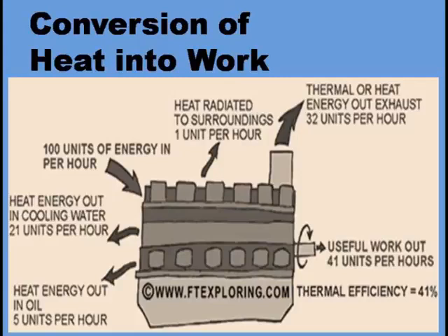If 1500 degree Celsius is reached inside the cylinder, cast iron or mild steel can melt. Cast iron can melt even at 1150 degree Celsius, and aluminum can melt at more than 700 degree Celsius. So if temperature goes above a certain limit, there are chances of these cylinders melting.